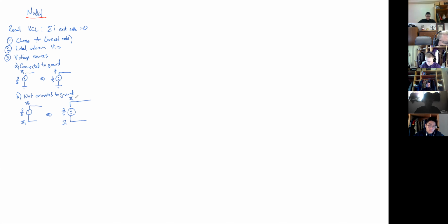This will have to be V1 plus 2 over S. And when it comes time to do your nodal analysis, you'll treat it as a supernode. So here, your regular node ended right there, but this whole thing will be part of a supernode. Down here, anything along this wire we'll consider V1 volts, and anything above on top we'll consider V1 plus 2 over S volts.